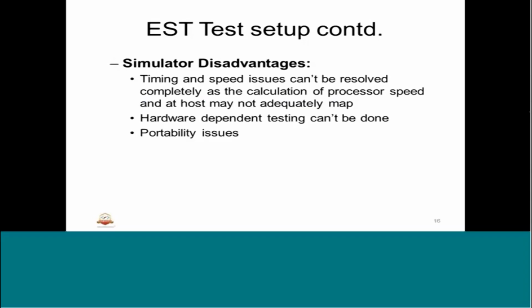One thing I remember in terms of simulator disadvantages is that, for example, the target system may have an 8-bit data bus between RAM and an unpipelined or memory mapped processor, while the host may have a pipelined processor, and it could be 32-bit. So there is a difference between the target system and the host.